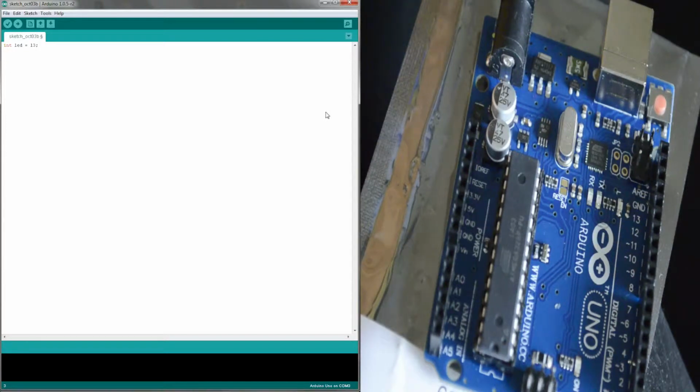Next thing we're going to do is actually run the setup, and I'm going to show you guys how to do that. So we're just setting it up here, void setup, and we'll end that. pinMode LED, OUTPUT. So basically what we did here, this is what is going to let the setup run, and we're initializing the digital pin as an output. That's basically what we did there.